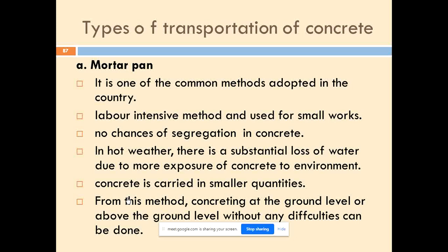Also, before using concrete in the mortar pan, the mortar pan should be neatly wetted, because it should not be dry. If the mortar pan is dry, then whatever moisture is there in the concrete, the mortar pan will take up that water if the surface is dry. So it should be wet before the concrete is used, and at every stage it should be clean.